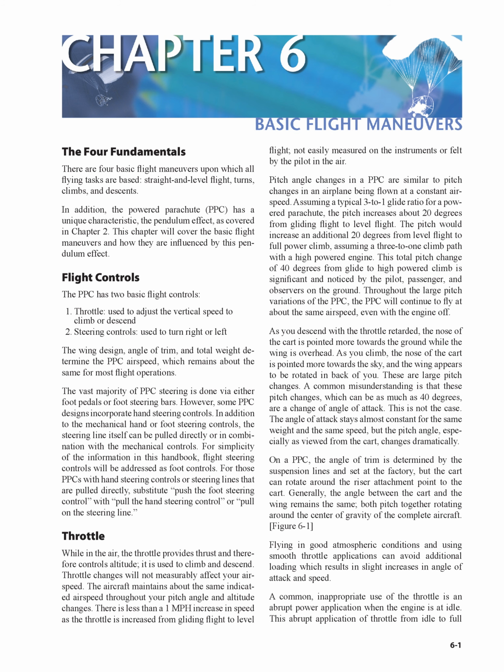The wing design, angle of trim, and total weight determine the PPC airspeed, which remains about the same for most flight operations. The vast majority of PPC steering is done via either foot pedals or foot steering bars. However, some PPC designs incorporate hand steering controls.